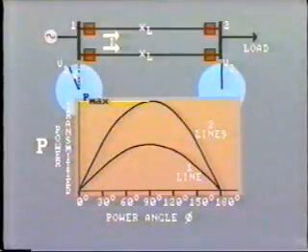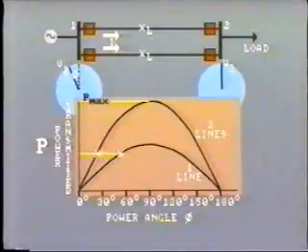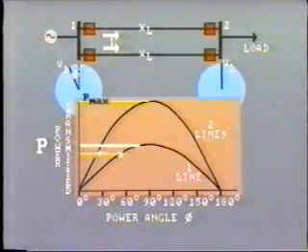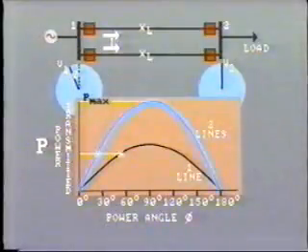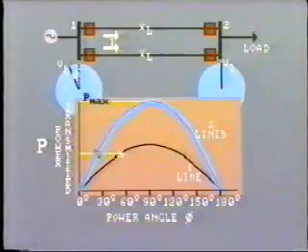On the curve, we can see that for every power transfer angle, the transfer capability has been doubled. For any particular value of load transfer, the load angle required is much less. Also, for any change in load, the required change in power angle is also much smaller. This means that with two lines in service, the operating point is a long way from the 90-degree limit of stability.